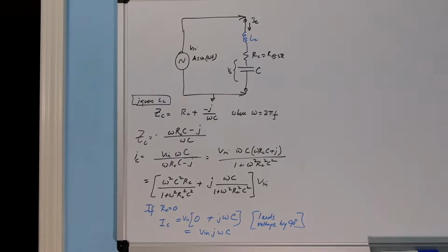So before we go into the actual measurements of the capacitor on a lock-in amplifier, let's review a few equations relating to the ESR, to the capacitance, as well as the phase angles of the voltage and currents, because that will become important in the actual measurements of the ESR and other parameters like the Q and dissipation factor and so on. So here we have a three-element capacitor designated with the two parasitic components, the inductor and the resistor.